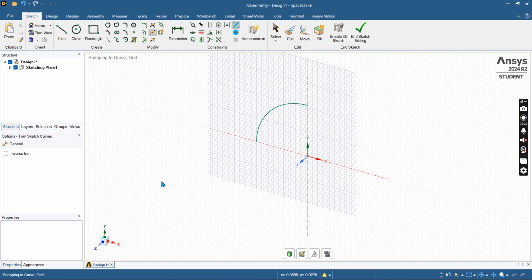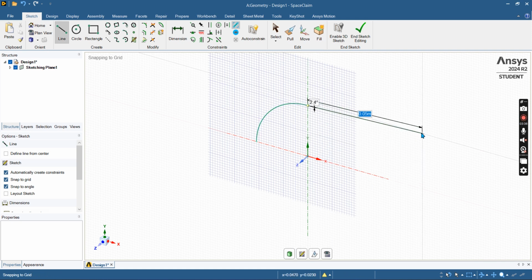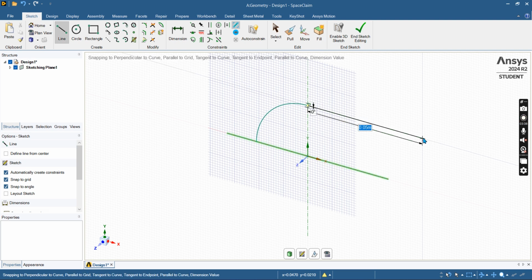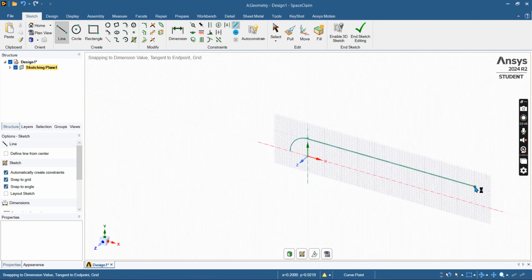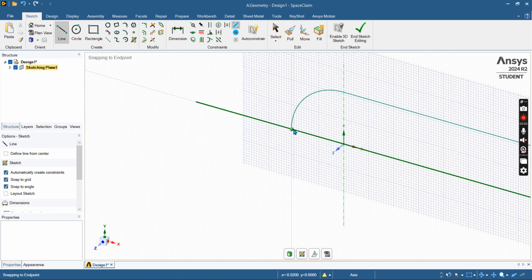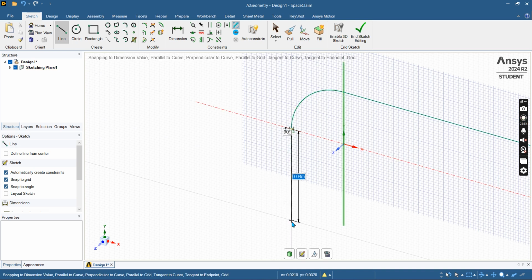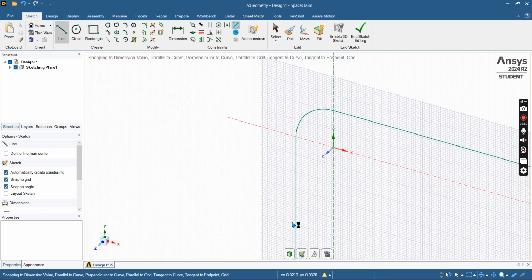Now I want the longer section of the pipe in the y direction and the shorter section of the pipe in the x direction. So for that I have to create the path first. So choose this point and give 90 degree, 0 degree, and change the length to 0.22 for the x direction, and escape and choose this point, choose 90 degree and change the dimension to 0.5 and enter.